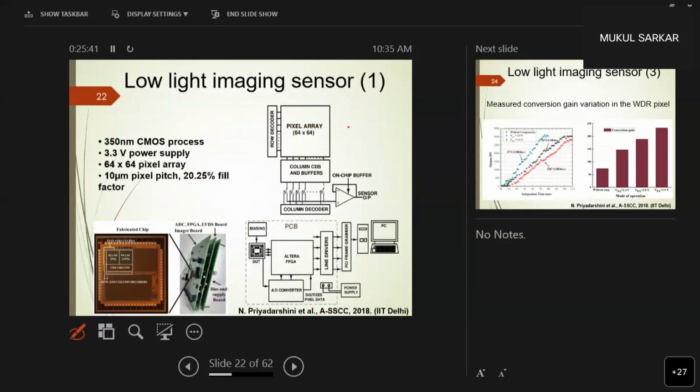So this was the sensor array that was fabricated. This is the microchip that you see that was fabricated. It was fabricated on a 350 nanometer AMS opto process. And these are the test bench and the test structures designed to test these pixels.